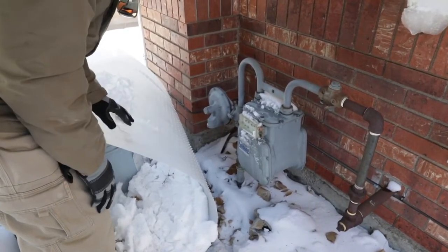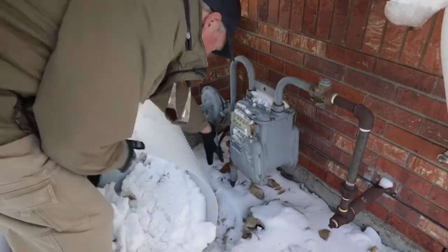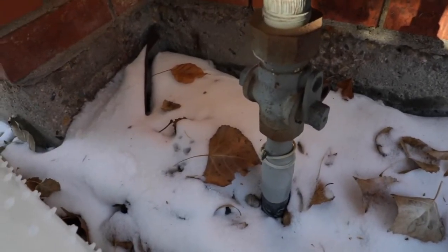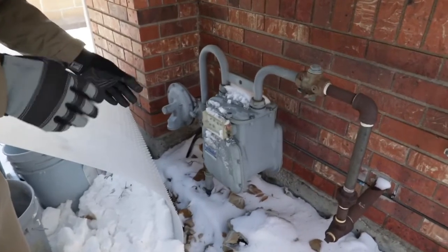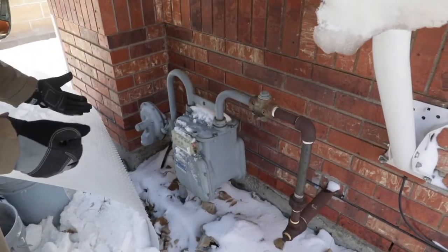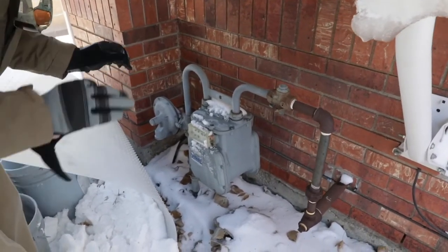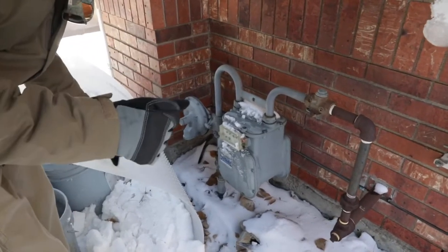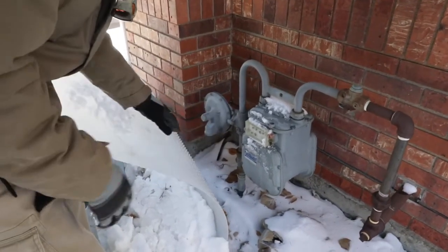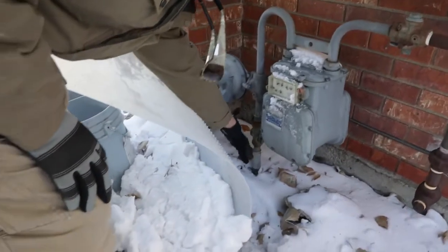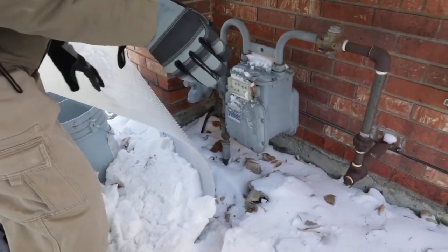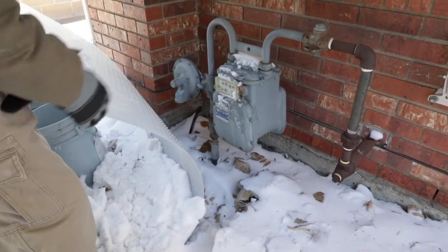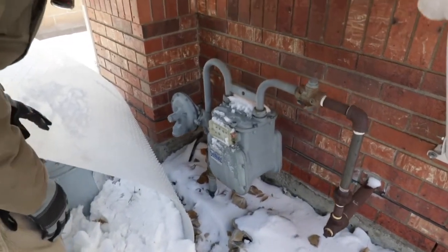And see if I'm actually finding a leak somewhere. The other thing is, our little wire down here is a tracer wire. Remember that the gas line from the street is PEX, it's plastic, so if they're trying to do a locate on it, they can't energize that plastic line, so they run a wire along the side of it, and they can energize that wire and locate their gas line out in the yard for whatever reason that might be.